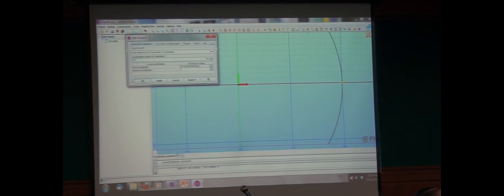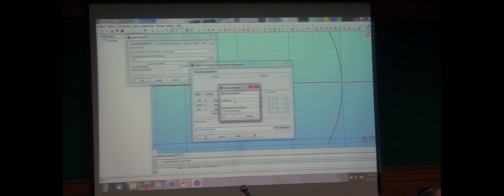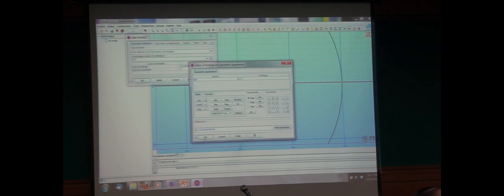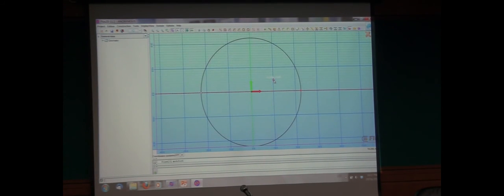So first thing, I'm going to take a circle to do the outer radius of the rotor. And I'm going to come here. And by the way, if I want to change it, I can put exactly the value. I could also enter a parameter here. It says that it's the outer radius of the rotor. And well, I could type in a better way, ORR. And then just put a value and say, okay, it's 22.5. Why not? I don't really care. And so that's the one I want here. You just clear and say it's what I want, okay? And now my circle here is depending, of course, on this value I just entered.